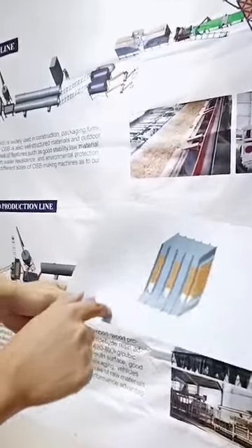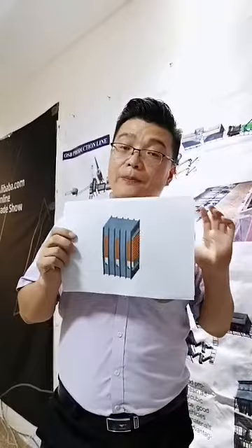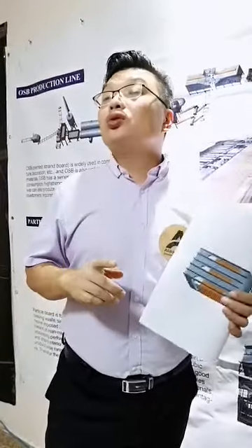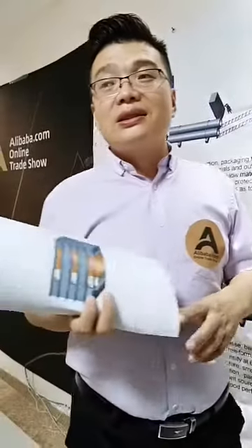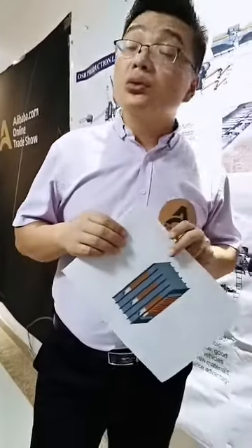Then for the hot press, we always design it with 1,200 tons of pressure, and a big difference from the common press is the hot plating. For example, if the particleboard is 4 by 8 feet, generally speaking, for plywood the hot plating is maybe 2,700 by 1,370. But for particleboard, the size will be 2,600 millimeters by 1,400 millimeters.